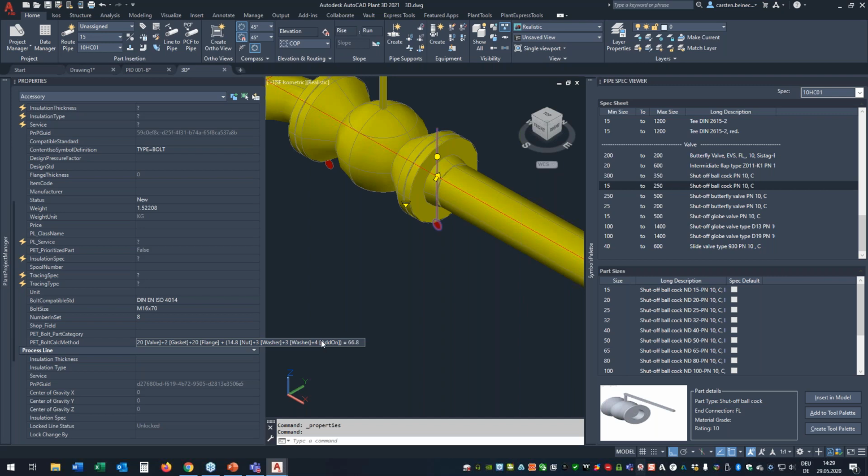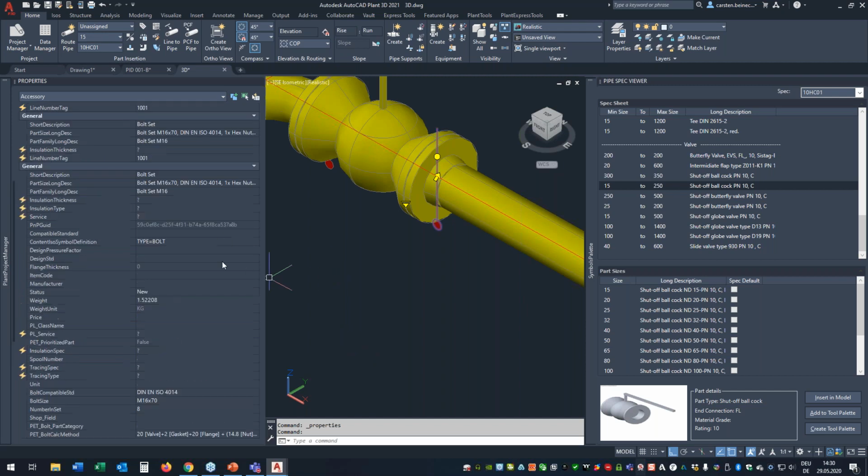Of course, you can use stud bolts or lug bolts, or here machine bolts, anything. You can have valves, and it's all sorts of combinations. We are pretty sure we covered everything. And you see the theoretical length would be 66.8. So the next available length in the catalog we provide, and you can of course extend that, is then a 70 millimeter bolt length.